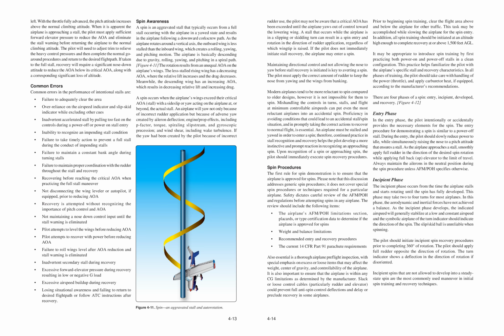Excessive forward elevator pressure during recovery, resulting in low or negative G-load. Excessive airspeed buildup during recovery. Losing situational awareness and failing to return to desired flight path or follow ATC instructions after recovery.